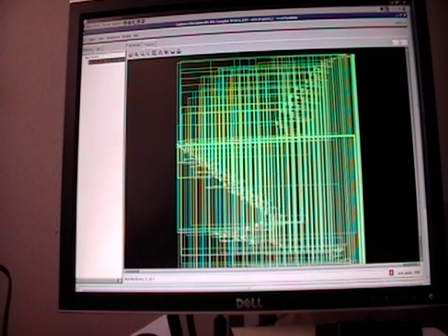Okay, so this is just an example of what happens to your VHDL or Verilog before it turns into a chip. It needs to be turned into gates, and then each one of these gates, there's another piece of software that turns those gates into transistors that I won't show you this time, but take EE431 if you're interested. And this single design here, when all is said and done, was about 100,000 transistors. And notice we just did that in a matter of seconds.